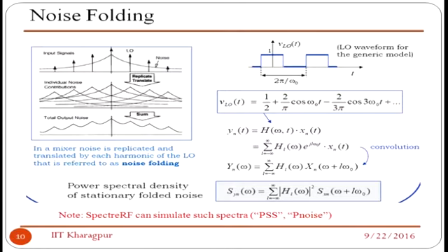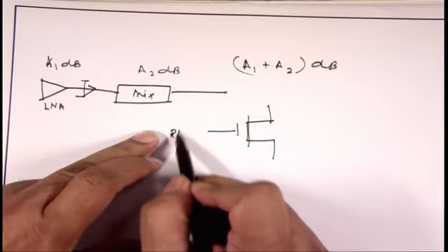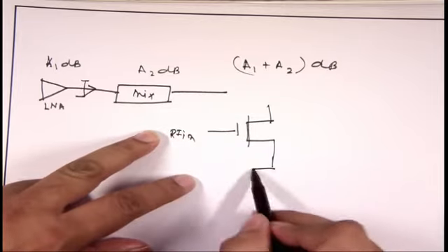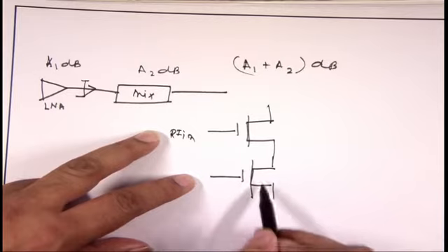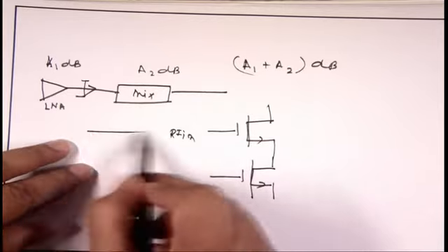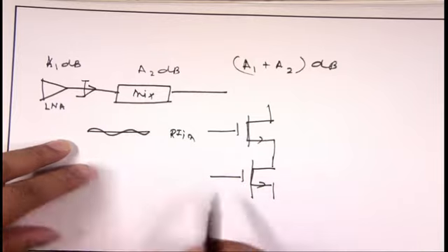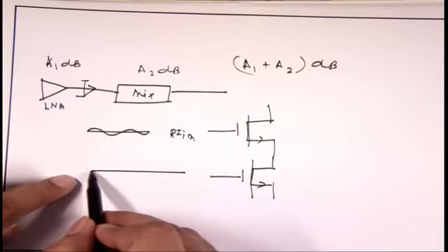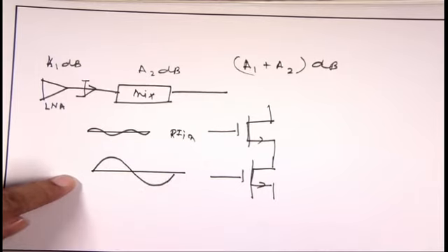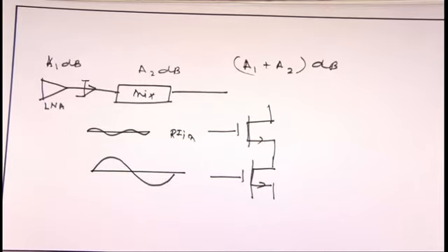It is your RF in, and it is your local oscillator, fine. And then you are getting a sinusoidal signal of low amplitude. You are also feeding a sinusoidal signal with large amplitude. You know that if I am giving a sinusoidal signal, then you expect only the fundamental to come, not odd and even harmonic content, right? But I would say that the case will be the same as with the square wave or rectangular wave.